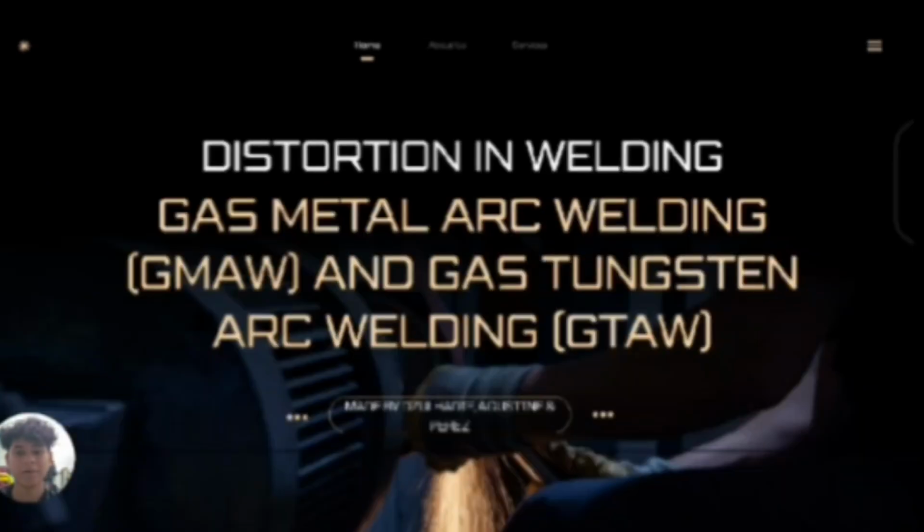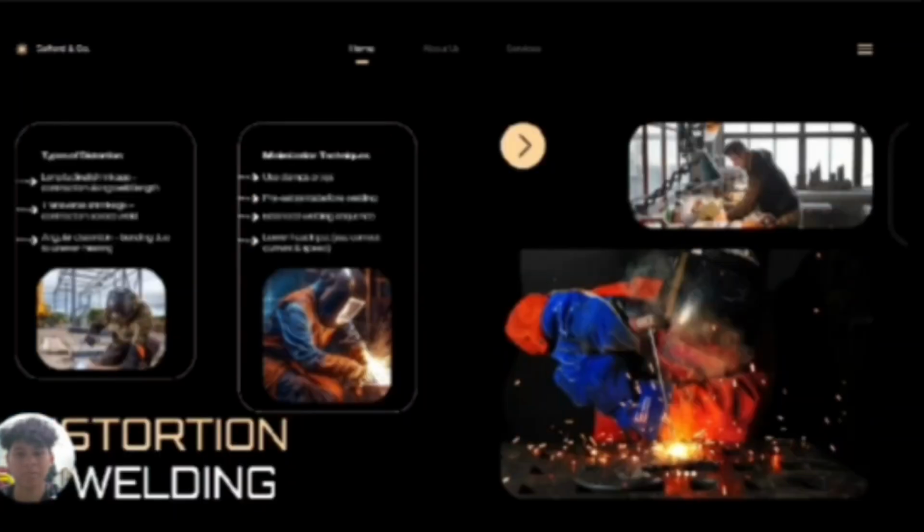The second quality issue is distortion in welding caused by uneven heating and cooling. We can manage this by using clamps or jigs, presetting joints, using a balanced welding sequence, and keeping the heat input low. This minimizes issues like longitudinal and transverse shrinkage.